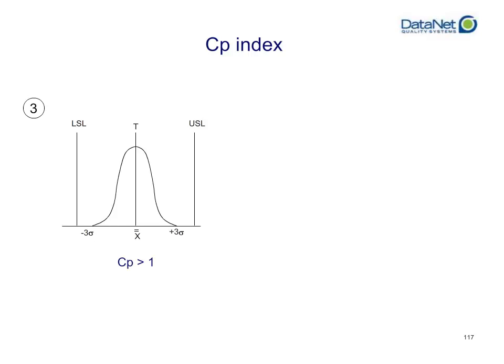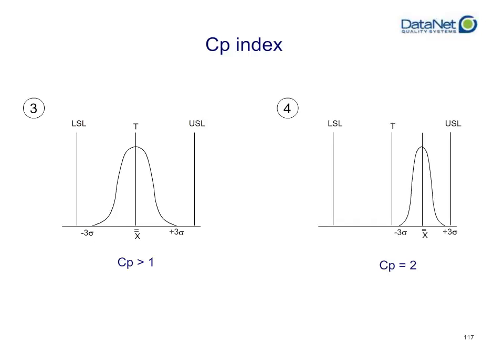In fact, if you want to quantify this, if your CP were to equal 2, that would mean that in theory, exactly twice as much of your data would fall within spec than if you had a CP of only 1. So you are twice as good, or you could theoretically produce half as much waste if your CP equaled 2 versus if your CP equaled 1.